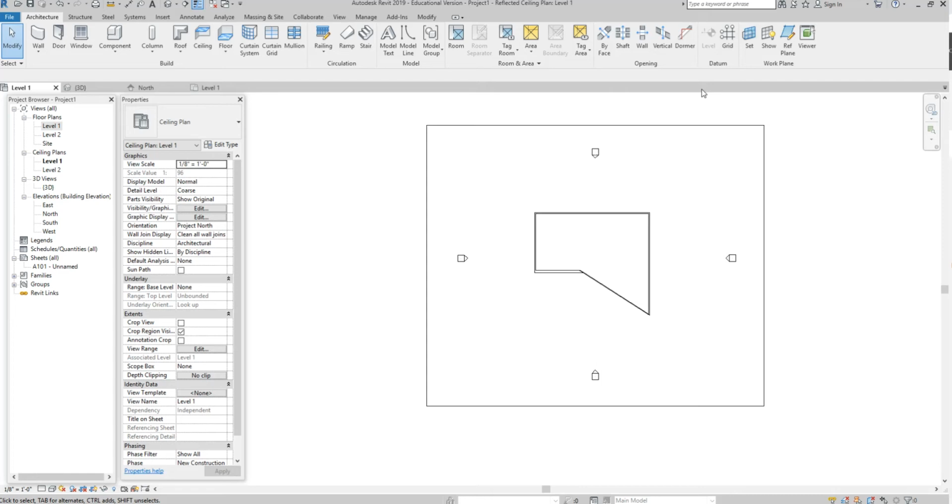I don't try to scale it down or make it smaller, thinking, oh, Revit's really tiny, I can't draw everything the right size. No, it's not true. Revit has adequate space on its drawing board to draw things the actual size that they should be. Okay, so here's our drawing board, and we draw things to the actual size that they are in the real world. All right, we draw things according to how we define them in Revit, meaning, generally in the United States, in an architectural application, we draw things in feet and inches. Okay, we don't use the metric system. So in our Revit drawing space here, we're going to be using feet and inches to draw things.